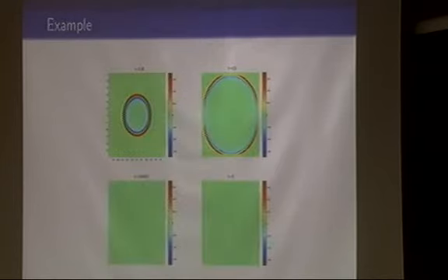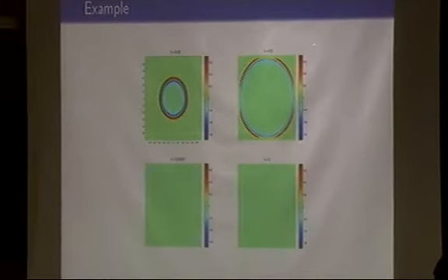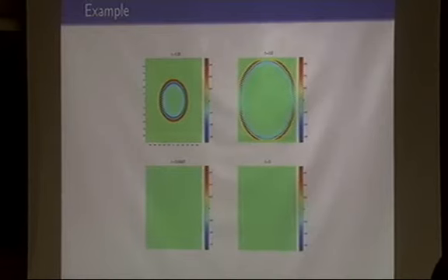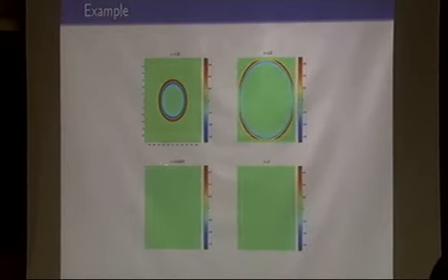So I will show you the solution here. I have some kind of source point, and then the wave propagates in all directions. I have the time levels here, and time propagates outward. And then you can see that in the PML layers, we say perfectly matched layers, the waves are absorbed. So we can put outside of the domain any kind of solution. This is zero solution, right? So the waves are damped, and the aim is that we don't have any big numerical reflections.